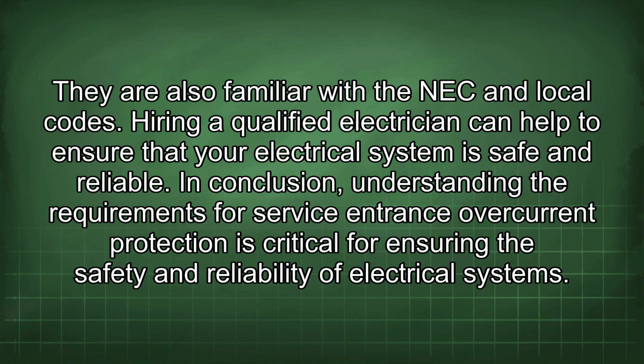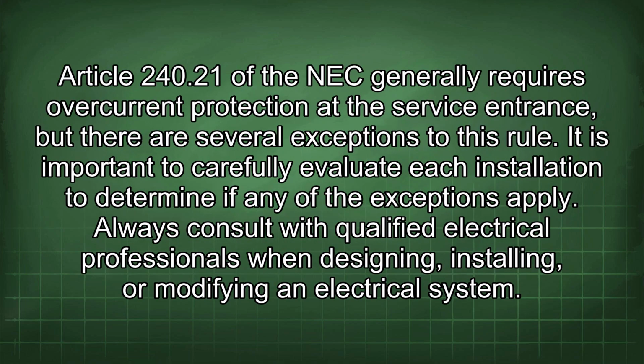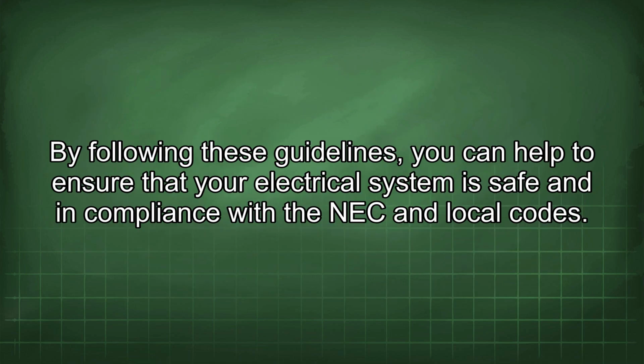In conclusion, understanding the requirements for service entrance overcurrent protection is critical for ensuring the safety and reliability of electrical systems. Article 240.21 of the NEC generally requires overcurrent protection at the service entrance, but there are several exceptions to this rule. It is important to carefully evaluate each installation to determine if any of the exceptions apply. Always consult with qualified electrical professionals when designing, installing, or modifying an electrical system. By following these guidelines, you can help to ensure that your electrical system is safe and in compliance with the NEC and local codes.